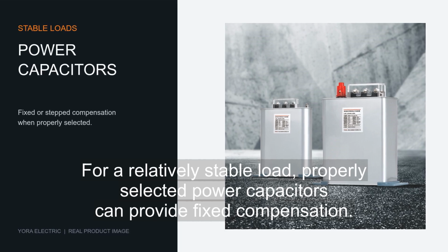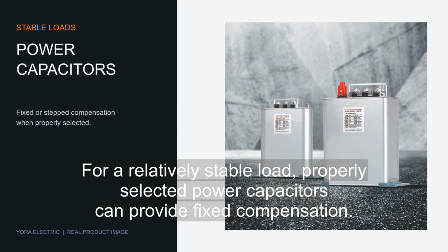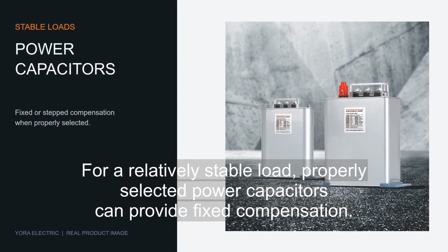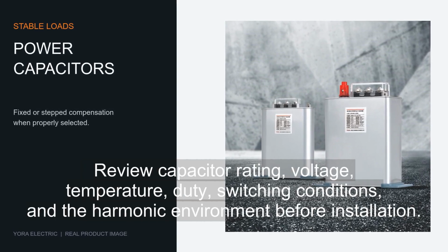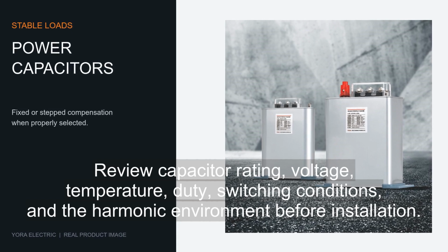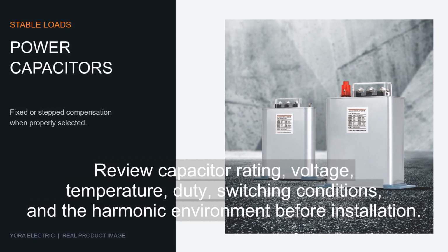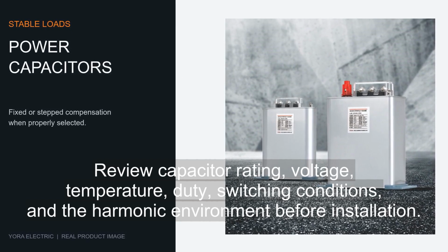For a relatively stable load, properly selected power capacitors can provide fixed compensation. Capacitor ratings, voltage, temperature, duty, switching conditions, and the surrounding harmonic environment must all be reviewed before installation.